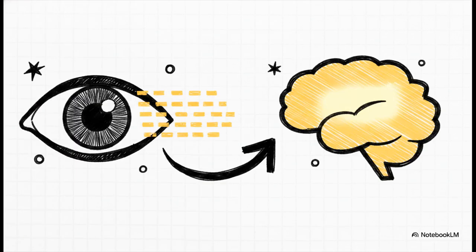But wait, if the screen is just rapidly flashing rows of lights, why doesn't it look like a flickering mess to us? Well, the answer is a biological phenomenon called persistence of vision. The human eye retains an image for roughly 1/24th of a second. If our LED module scans through all its lines more than 50 times per second, our biological hardware connects the dots for us, and our brains perceive it as a single, perfectly continuous, solid image.